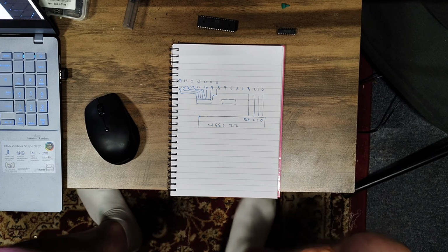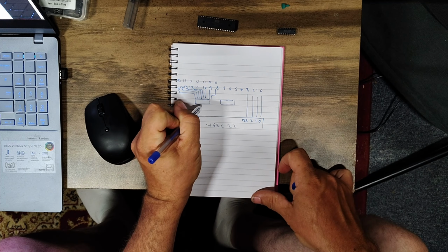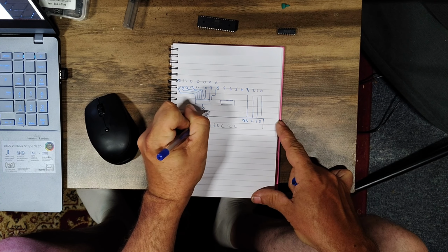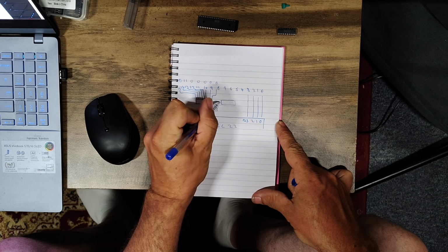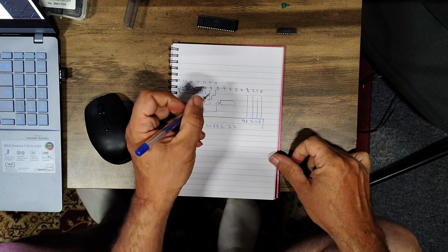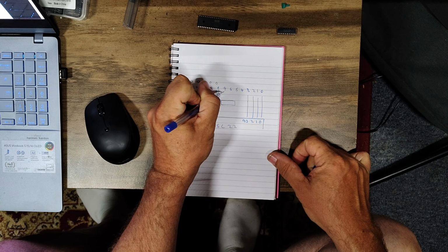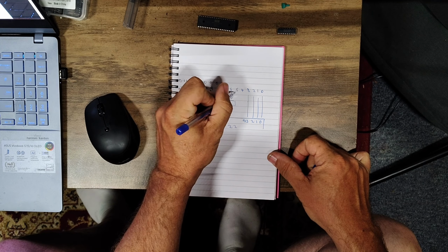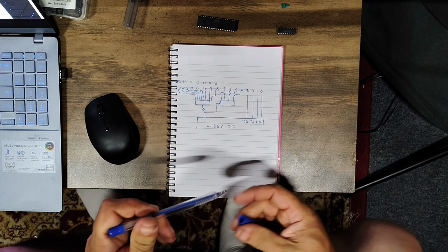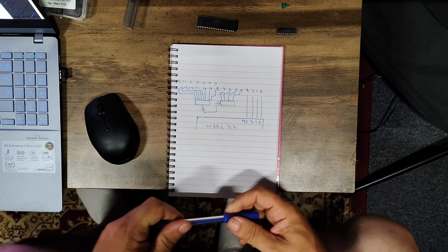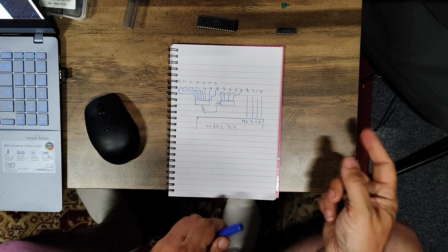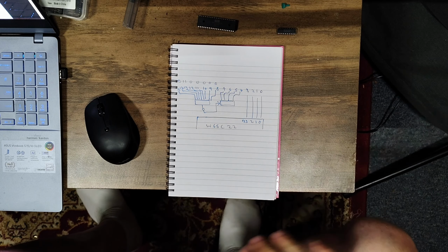For these first 8, if they are all perfect, then it will output a 0, which we can feed into this chip that will make it work. So if these are all perfect, this one's going to check for 0, 0, 0, 0. And by the way, the other 4 inputs on this comparator we're just going to set to be the same. We're going to manually tie them to be the same as their comparators, so they won't matter.